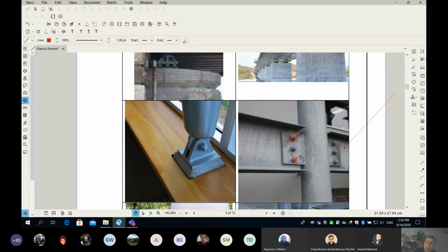Those two bolts will make it kind of subjective, because some of you will say, listen, Tahir, there is a distance between this bolt and this one, and this distance is something called the lever arm, which means they potentially have a little bit of resistance for the rotation. That's why Hamid's was the best theoretical answer. Yes, it is semi: it's not really fixed or really hinged, because there is some allowance of rotation, but not 100%.